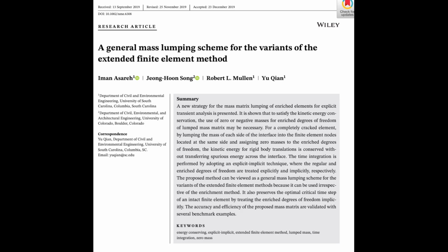Here's the problem again. When we use XFEM for dynamic events, and that crack gets really close to those connection points, those nodes, in our digital model, the critical time step issue comes back. Exactly. The critical time step, the biggest time jump the simulation can take while staying stable and accurate, can suddenly become vanishingly small. So the benefit of XFEM not having to redraw the mesh is almost wiped out because the simulation just crawls along. Precisely.